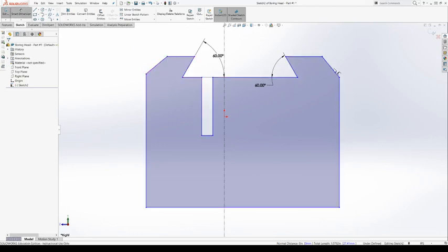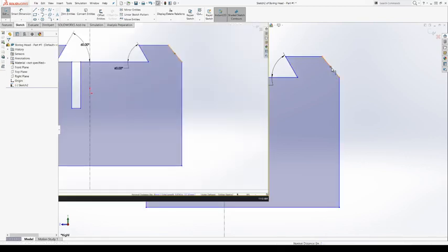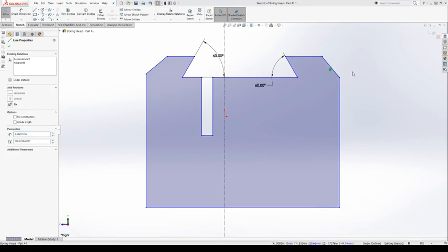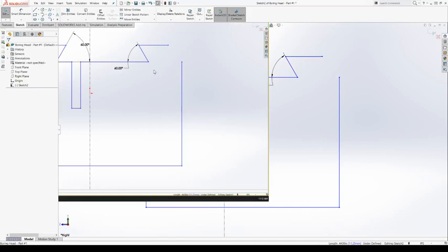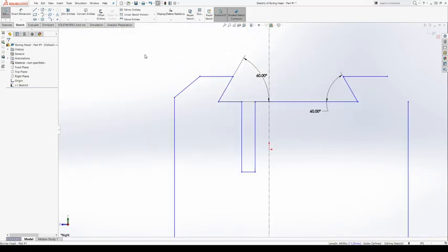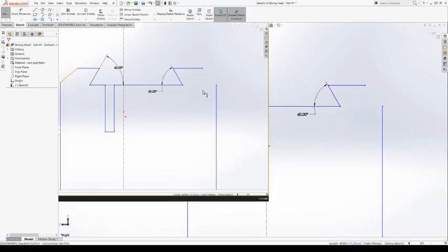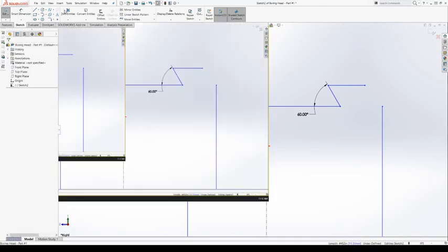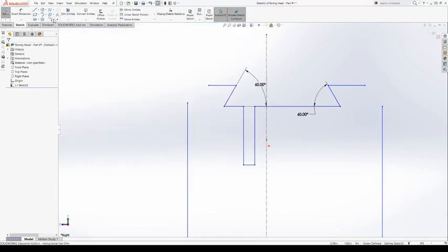Pretty straightforward. I'm going to delete these chamfers real quick, because really the better way of doing this, because both these chamfers are the same size, is to use the chamfer tool over here. My sketch fillet, sketch chamfer is going to work basically the same way as Mastercam.